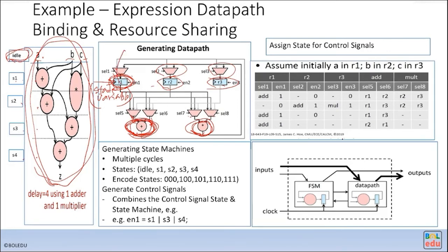Right now, the problem is how do you decide the mux select and the register latch control? You need to decide all those control signals. What I'm talking about is, when as a human we design the RTL code, we are doing the same thing, but we are just doing it manually. The design process as you design RTL code is exactly the same.